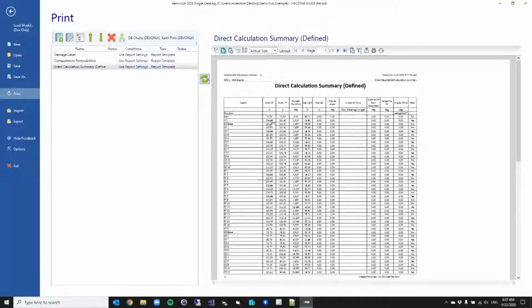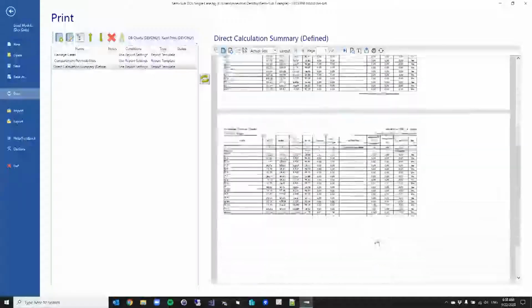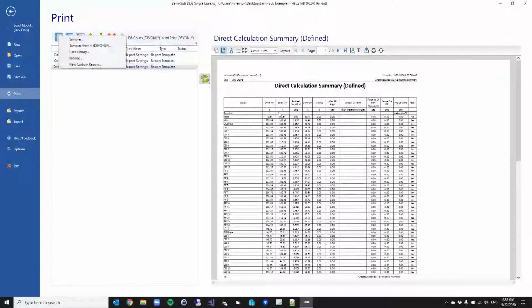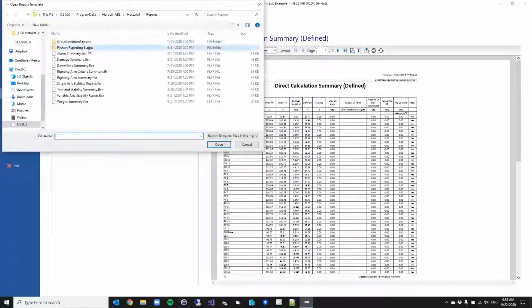So in this case, I can have a one-line summary where I have all of my results in one place, set up as a table saying, yes, here's my load case 1, everything passes under that. Here's my load case 2, everything passes under that as well. I can add a report using the database definition or templates basically. We can also do the same thing with a Python script as well.